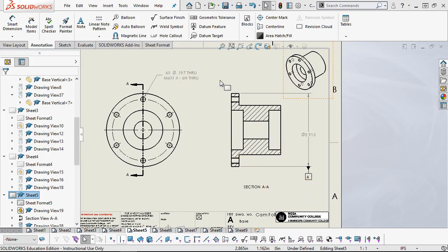All right. So having done that, the bores are the ones that, maybe this is A, this becomes B, and then even one of the bearing faces could be a C, so that we could relate the other one as a position to all 3. All right, so I'm still kind of juggling that one. Let me know what you decide.